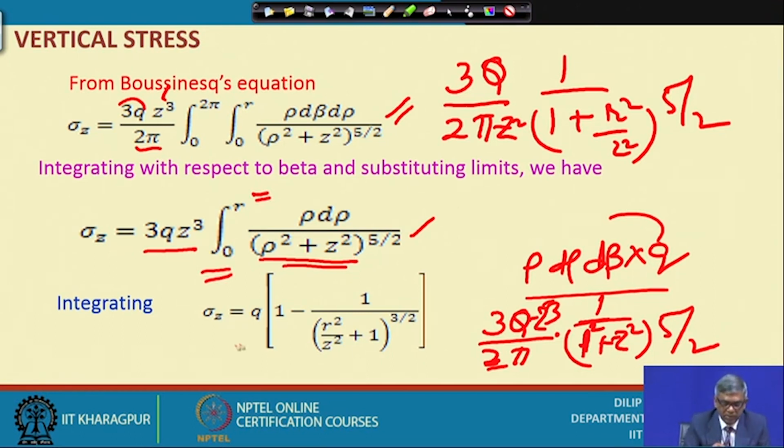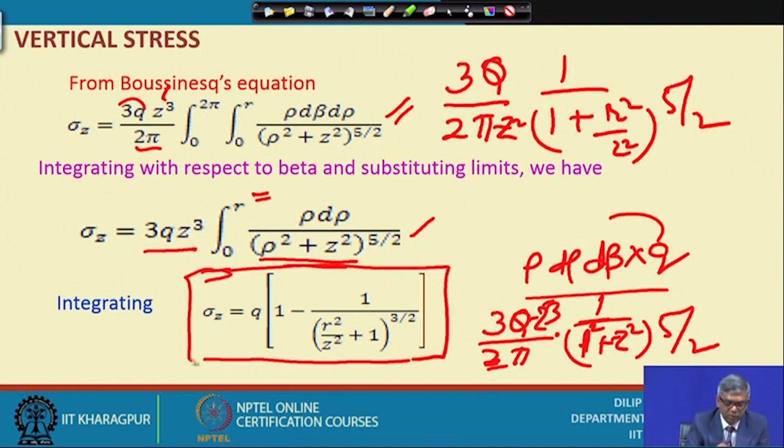If I put that in, then finally I get an expression like this: sigma z equals q into, that is, q is actually the intensity of the footing applied at the surface. This is the surface footing intensity q, and at any depth it is q times (1 minus this). So even as we go deeper and deeper, the stress will obviously be less, and through this equation we can get that.